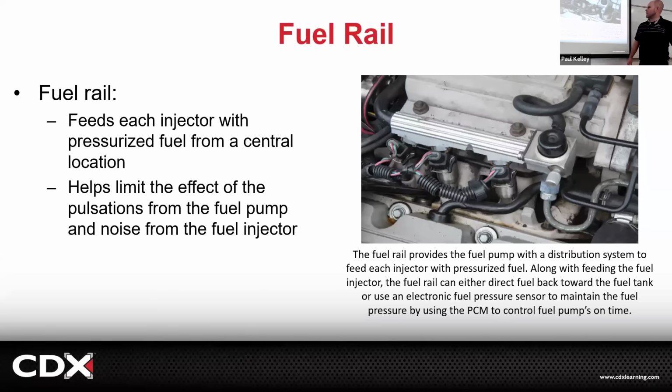If you take this apart and that O-ring tears or gets rolled off or something, you'll have a fuel leak onto these parts that could catch on fire. So if you get involved in these, you've got to be very aware that the upper O-ring that sticks into the fuel rail can't be ripped, can't be rolled. I like to use a silicone paste, and that'll really lube the O-ring well. When you go to pop the injector in and the right grease is on there, it fits just right. You can tell it feels good.